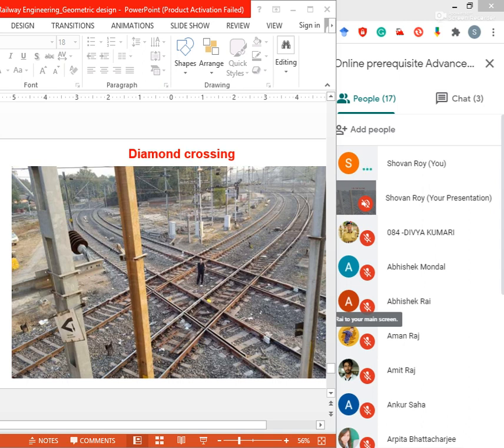One figure is there; you should follow it from the book. The B class station is the most common type of station and is provided on single line as well as double line sections. At a B class station, the line has to be clear up to an adequate distance beyond the outer signal before permission to approach can be given to a train. The minimum signals required at a B class station include the outer signal. An outer signal is the first stop signal. The outer signal can also be below the Warner.